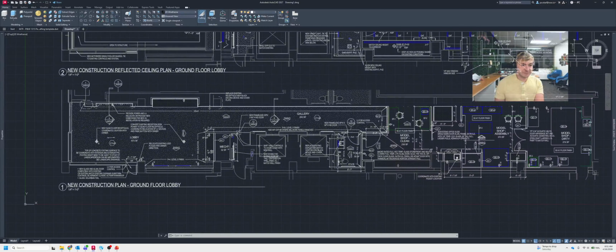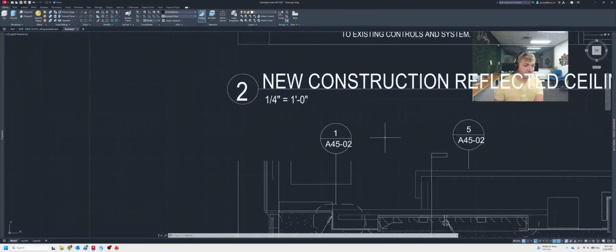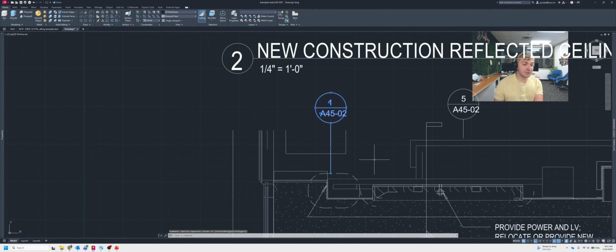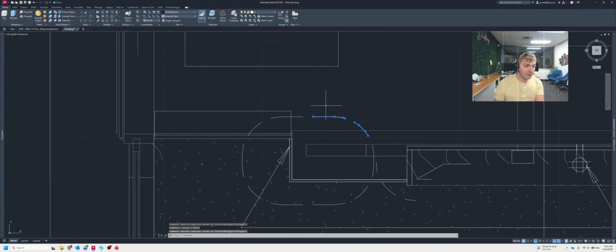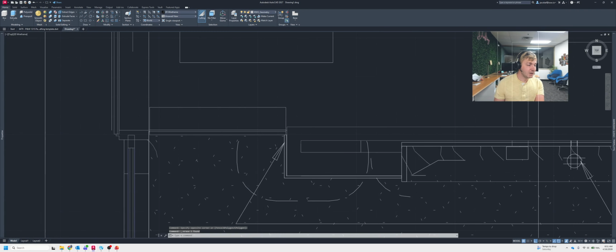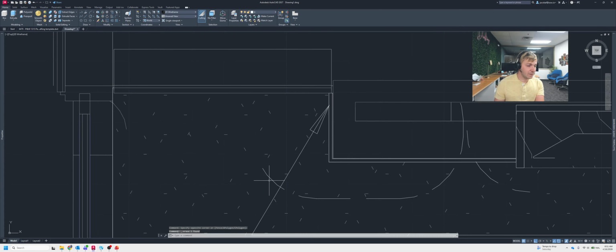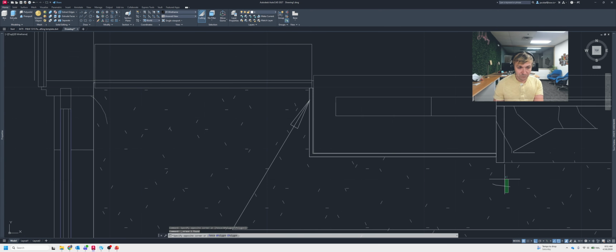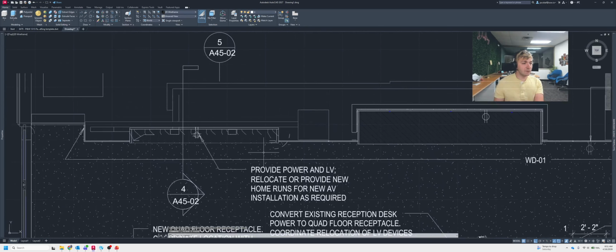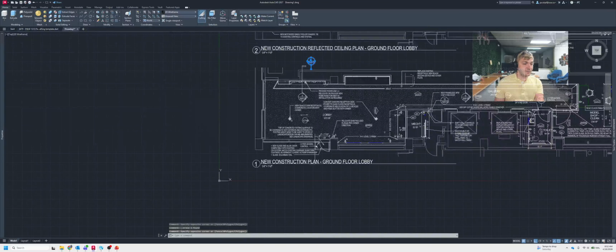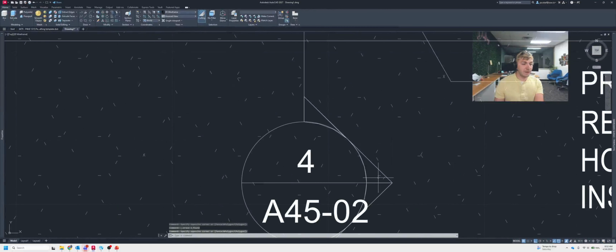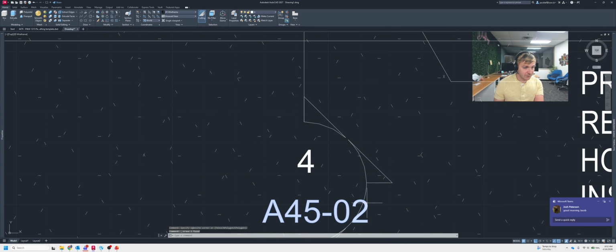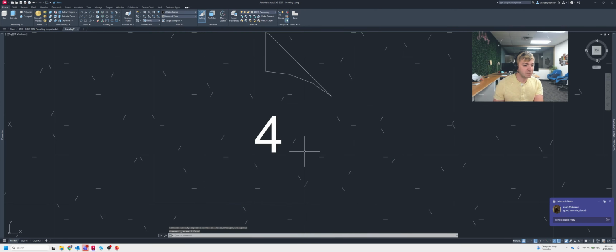Once you've deleted that, next up, you probably want to go through and clean up things like if there's any elevation or section calls, they won't be relevant to anything we're doing, because we're going to create our own. These are referencing architectural drawings. Of course, they don't relate to the on-site shop drawings, so we need to get rid of those. So again, anything like that that is kind of just in the way, we're going to be removing those.